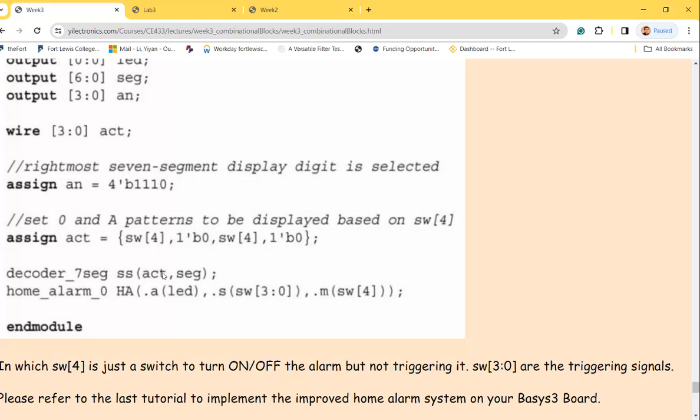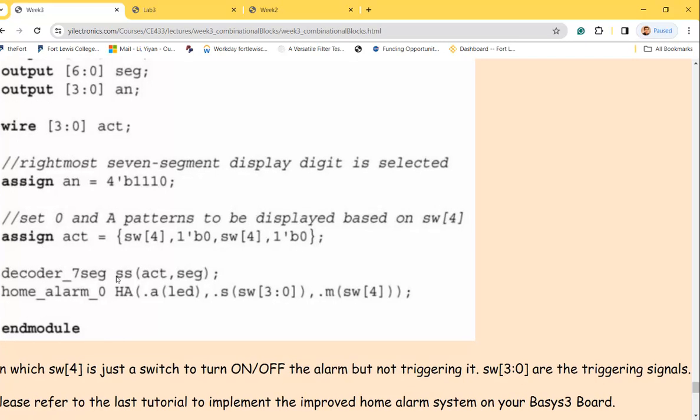So in the top module, you include a sub module, right? Then you make the connection with the dot something, parentheses something. But this one doesn't have any of the dots, which is okay. It's just trying to make it simple. It's the same way to make the connections from these signal lines to the signal lines inside the module, but I have to follow a certain order.